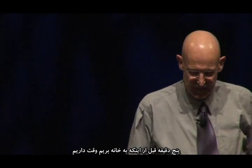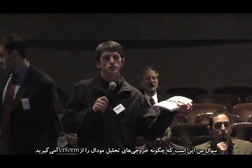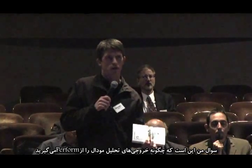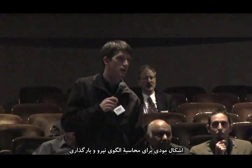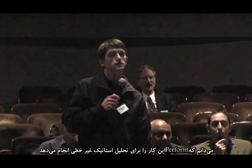That's the important thing. Okay, we have 5 minutes before we have to leave the house. Any questions? I guess my question is, how do you get the modal analysis output from Perform? So why do you need it? The mode shapes to calculate the force pattern. I know Perform will do it for you in doing a pushover analysis.